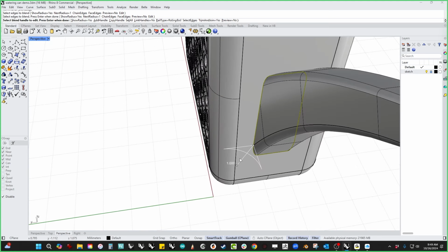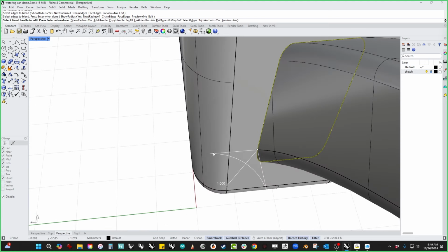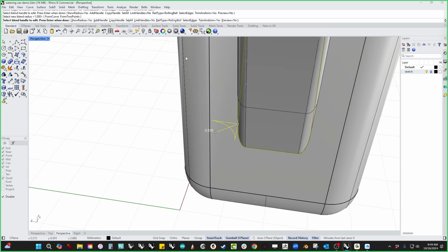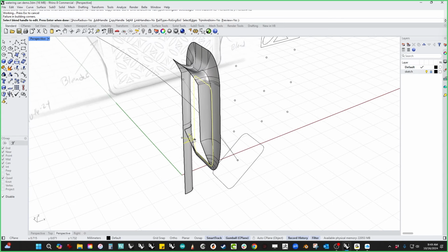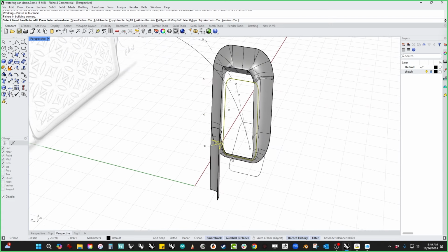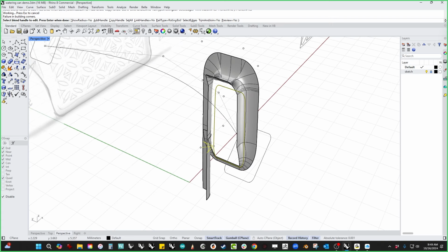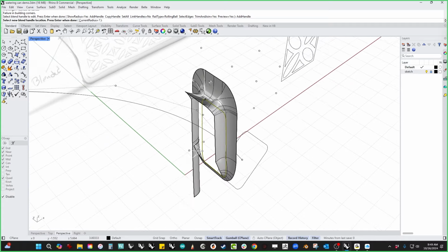And the first thing you'll notice is that the preview is hooking over the edge of this. That's going to fail instantly. So I actually have to make this inside so that it's on the same surface. And if we preview this, it's going to probably make a giant mess. The reason is that this fillet down here is way bigger than that fillet down there. So we're going to add some handles.